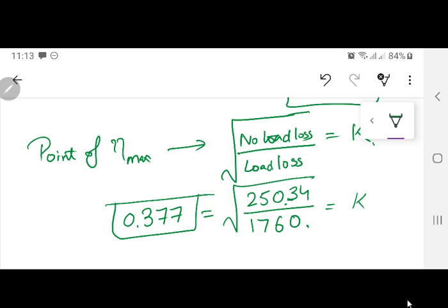Only at night or in the evening, when more televisions and air conditioners are on, is the load different. Otherwise, the distribution transformer exhibits a normal variable load in the range of 35 or 40 to 50%. So in this case, you are getting 37.7%.